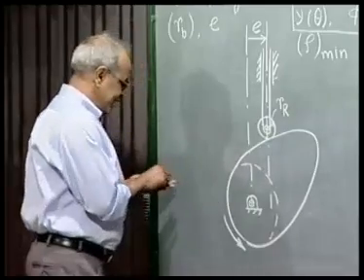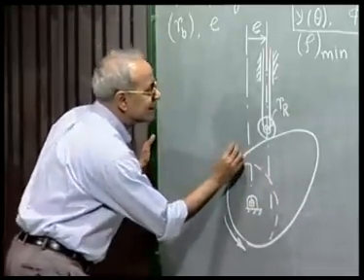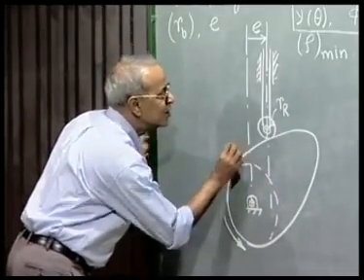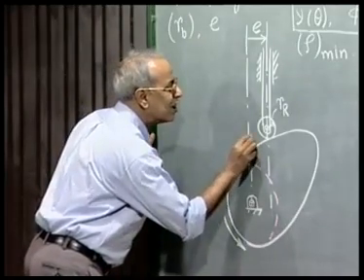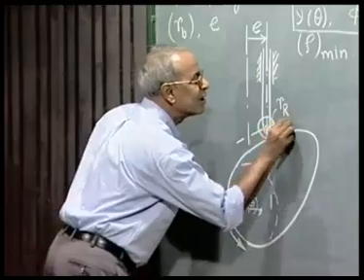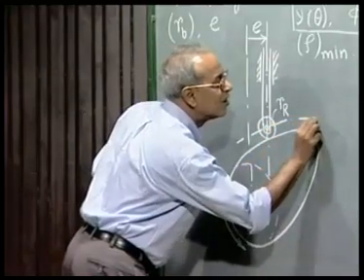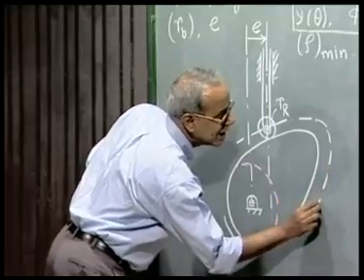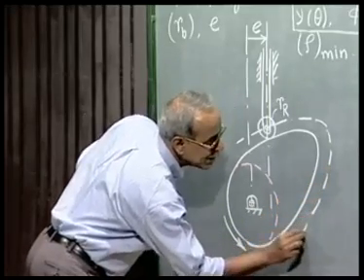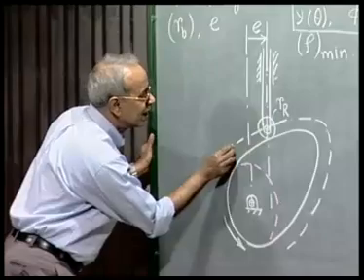So if this is the base circle radius, then if we draw the pitch curve, which is a curve parallel to the cam profile, the distance between them everywhere is the roller radius.